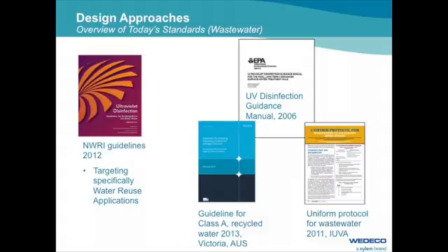And this UV disinfection guidance manual actually was predominantly developed for drinking water applications. So when this concern about Cryptosporidium and Giardia came up, and the notice that chlorine is ineffective against those pathogens, that was developed, and the way it is written, it's so flexible and gives so much guidance that it's also well applicable to wastewater.